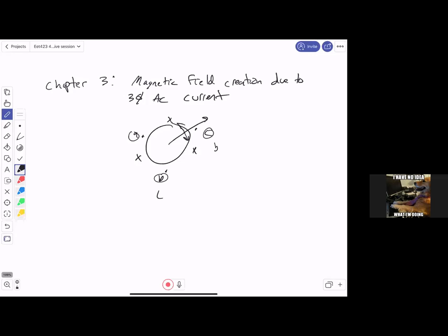You just connect them to whatever phases you want, and then you just check rotation. So you can swap these in any direction you want, and you're still going to get that magnetic field that rotates along, and its direction is going to be based on doing your right hand rules, wrapping your fingers around the winding and then pointing your thumb.